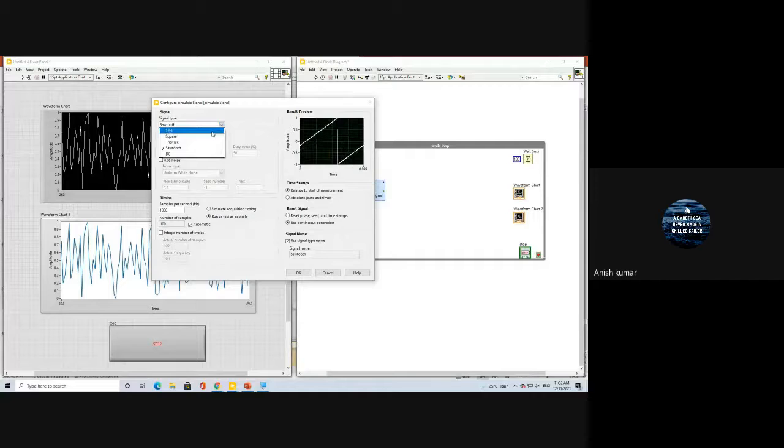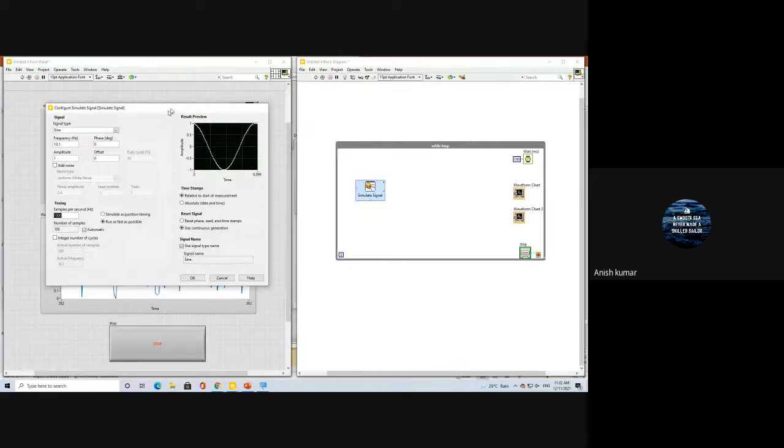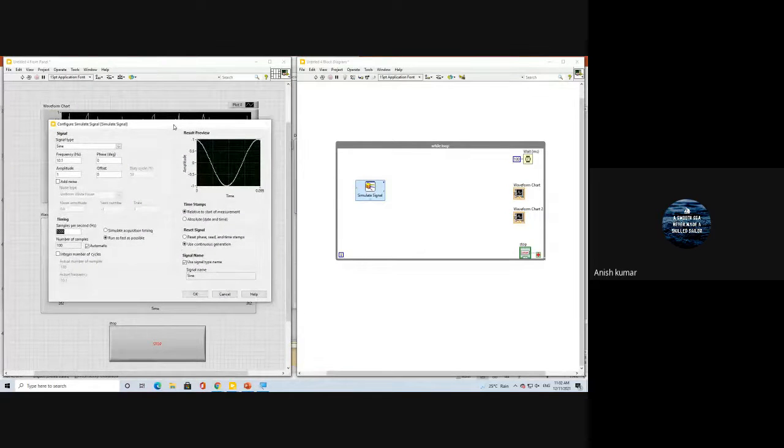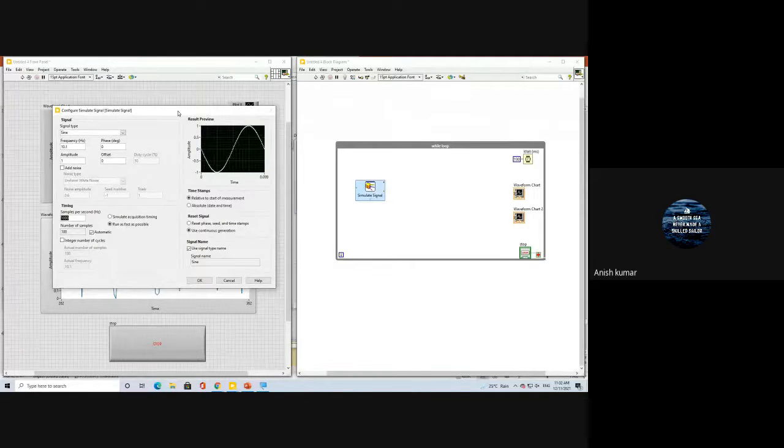So now I will introduce the sine wave itself, and you see the frequency is 10.1. Here is the sampling frequency, and when you are involved in this, you must know what the Nyquist theorem is. So what is the Nyquist theorem? Sampling frequency must be greater than or equal to two times the message frequency. This greater than or equal to is an important sign.